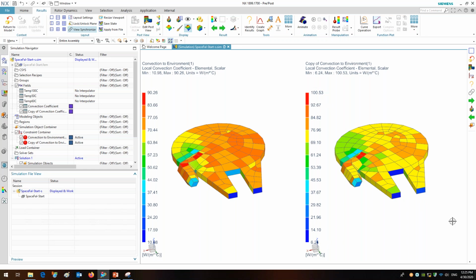So for this particular model with this particular mesh versus fields, it appears like I would probably be better off with the nearest neighbor. This was just 2 of the different interpolation schemes. There's still, I think, 5 other ones we could try and check to really pick the one that's best suited for this data and this model.